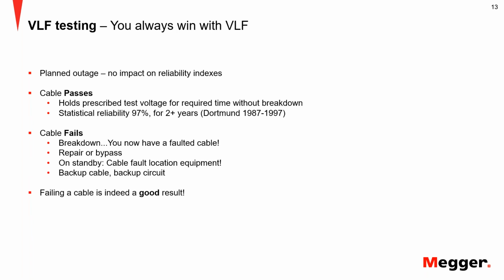And then, as I always say, you always win when you do VLF testing, because first of all, you're doing this in a planned outage. So whatever happens, nothing happens to your index numbers, okay? So your SAIFI, SAIDI, CAIDI, CAIFI, no impact there. If the cable passes, congratulations. International studies now show that in 97 out of 100 cases, your circuit will be quiet for the next 3 years from aging-induced faults.